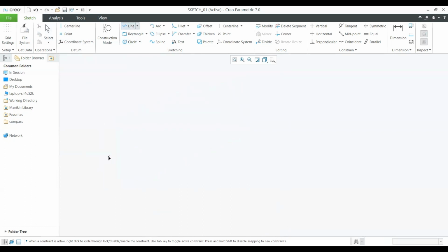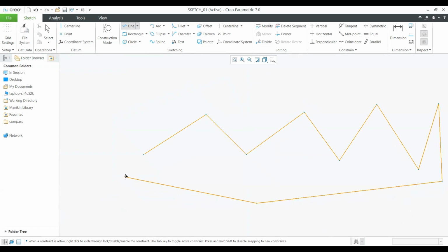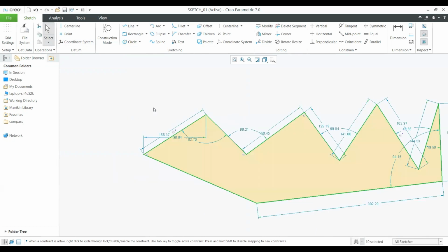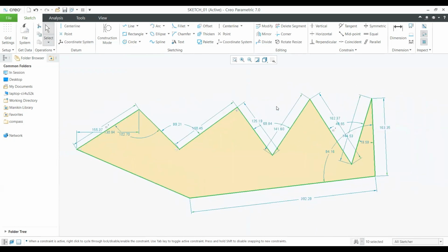So what is the line command? Line command is basically used to create a line or a straight line, which we can easily create. So for this, we need 2 points. First point, I am selecting it. Second point, I can create it. Any drawing you can create, and I close it. Press the middle mouse scroller button for exiting the command. I am just creating a random drawing.